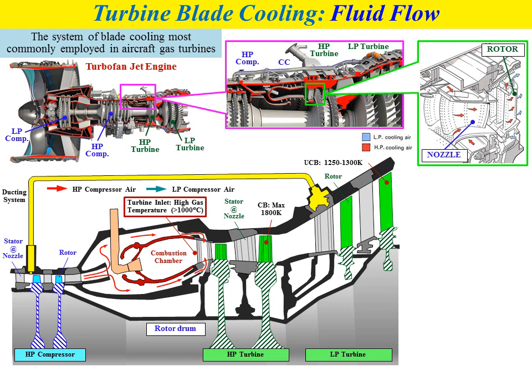For this case, the high pressure cooling air will enter the first nozzle of the high pressure turbine from the bottom and also from above the nozzle. These features depend on the design of the blade. And the high pressure cooling air can also enter from the bottom of the rotor blade of the first stage of the high pressure turbine.